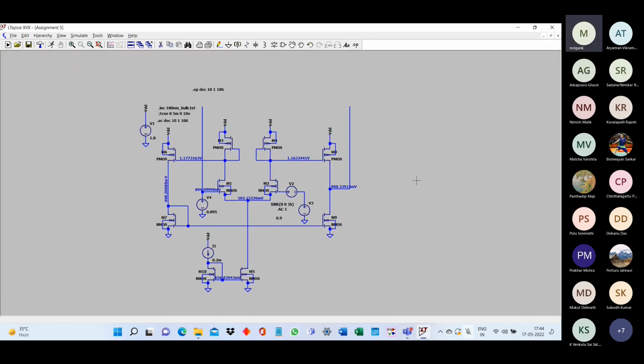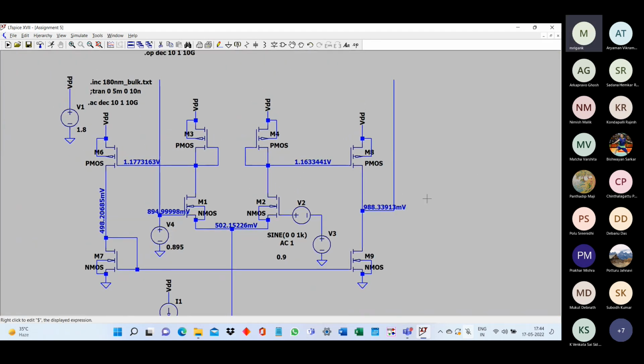Yeah, so this is okay. Now we have again come back to the appropriate DC bias point at the output. This is just to ensure that all the transistors are remaining in saturation. Remember, in this amplifier, the output stage does not have a stable DC bias unless it is connected in feedback. In the open loop circuit, we are simulating just to get the open loop gain, and therefore we are just sweeping the input DC to figure out the DC point. That's all. In the actual scenario, we will always be using feedback, and we will automatically get the required DC at the output. Whatever the DC at the input is will decide the DC at the output.